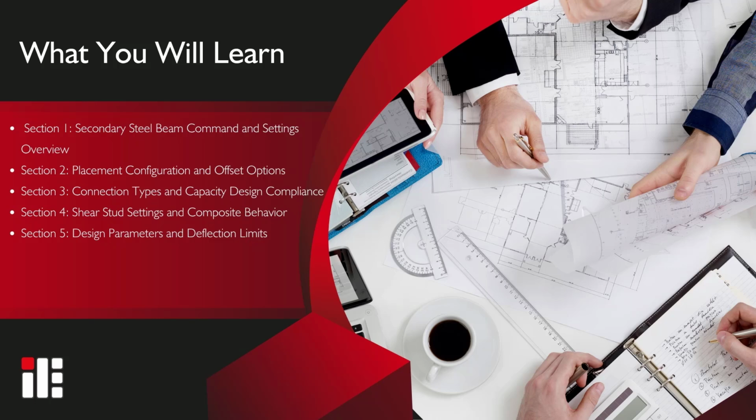modeling. Next, we'll explore shear stud settings and how they affect composite action between steel beams and slabs. Finally, you'll learn how to access and override critical design parameters, including deflection limits and stiffness-related checks. By the end of this video, you'll be equipped to model secondary steel framing systems with structural accuracy and confidence.